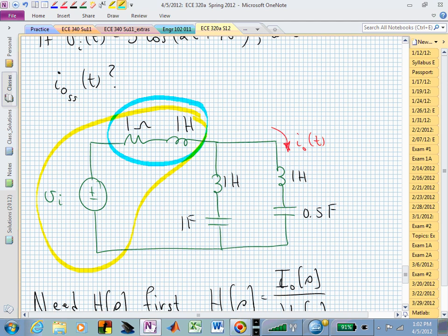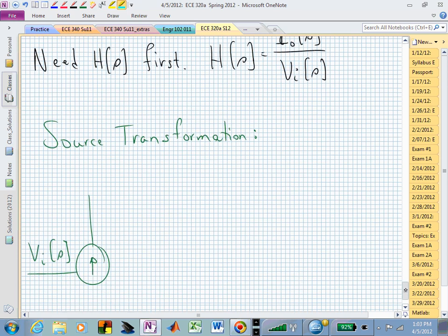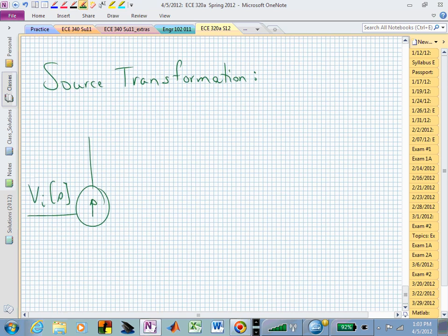And our inductors have what for their impedance? sL. So it's s times 1, so the L goes away, or it's not very explicitly there, but it is there. So we have s plus 1 for that impedance. That now needs to come here and divide our expression for the input voltage waveform's Laplace transform.